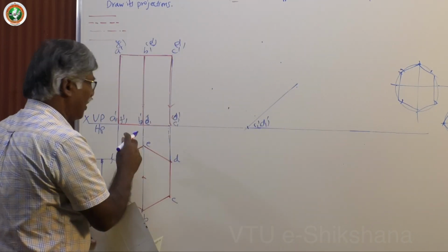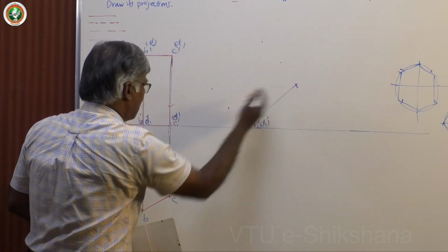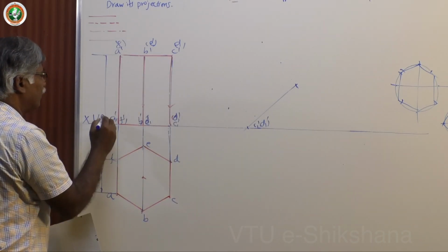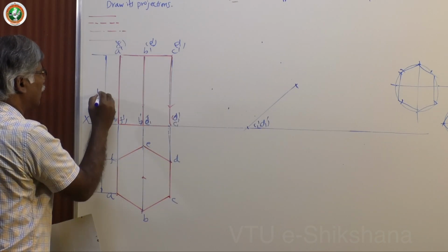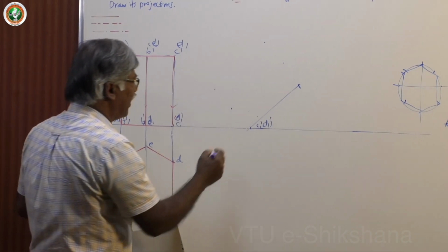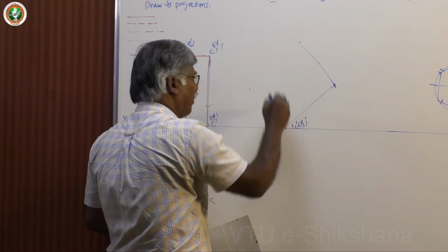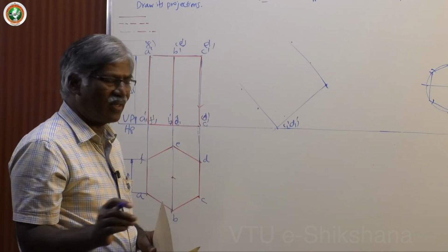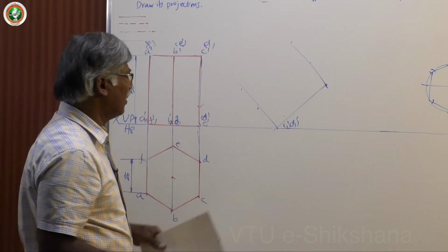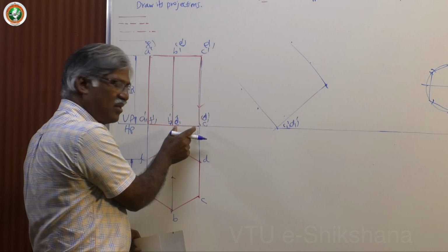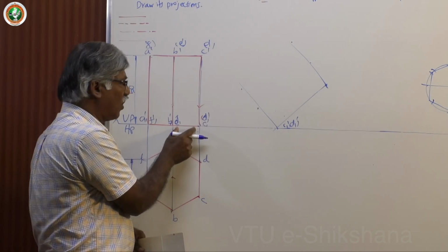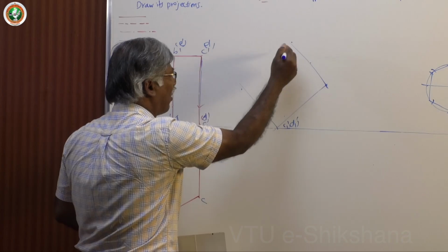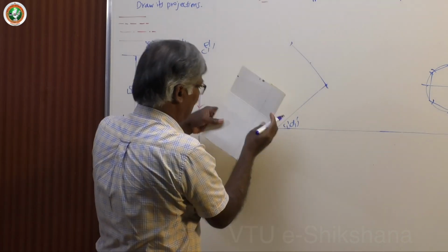What you do is, first you mark this distance. Actually this is given 50. Then draw two vertical lines, perpendicular lines, using the small protractor or any method, set square. Then take only one distance. That's all. That works for four arcs. Draw an arc here. Again with these two centers, draw arcs. Then you will get the figure.